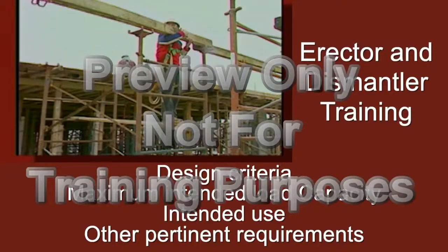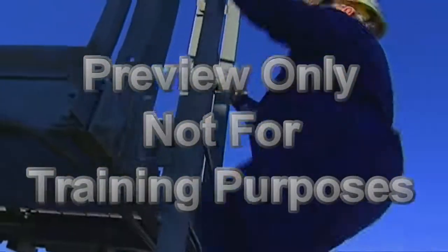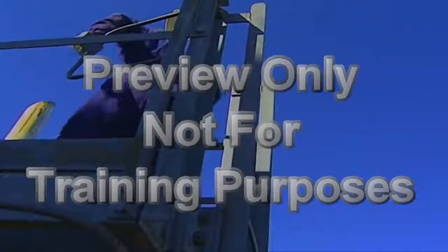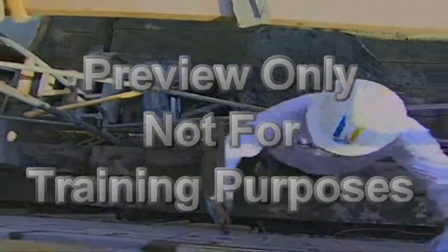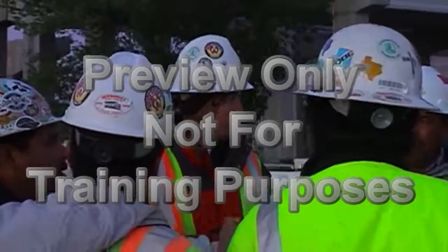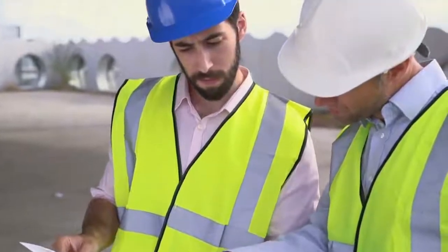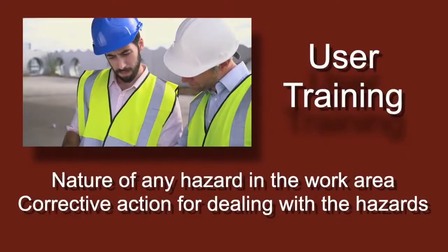pertinent requirements. Individuals whose work requires them to be supported by the scaffolding to be able to reach elevated work areas are referred to as scaffold users. OSHA mandates that scaffold users must be trained by a qualified person. Training must enable employees to recognize the hazards associated with the type of scaffold being used and to understand the procedures to control or minimize the hazards. User training will include the nature of any hazard in the work area and the corrective actions for dealing with the hazards.